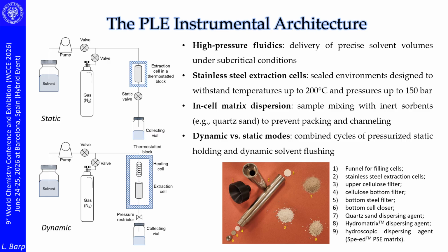Inside the cell body, the solid sample is never packed raw. It is systematically dispersed with an inert material such as quartz, sand, or diatomaceous earth to prevent matrix compaction and eliminate preferential solvent channeling, thereby maximizing the available contact surface area.